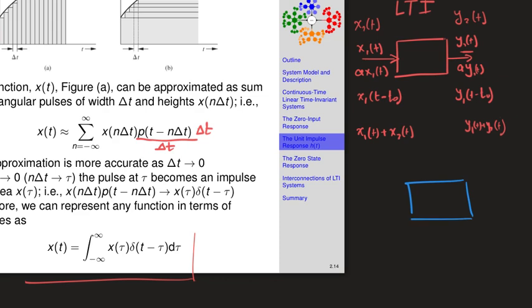If somehow I can go to the lab and put into my system a unit impulse and then measure the output from that system. So my input x of t is actually set to be a delta. I will bring my system, put it in the lab, and somehow from a generator, I will generate just a quick impulse, right, with very high amplitude, very short time duration, almost zero, so very quick. And I'll put that, and then the output of that system, I'll connect it to a spectrum analyzer or maybe an oscilloscope, and then see what the output is going to be.